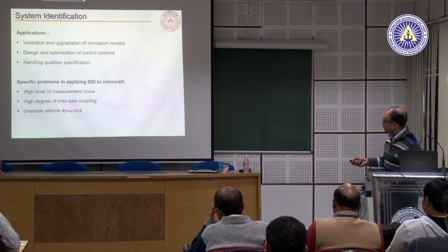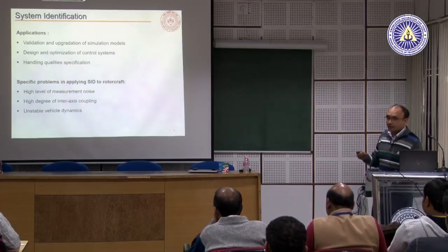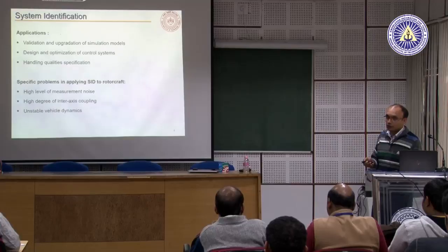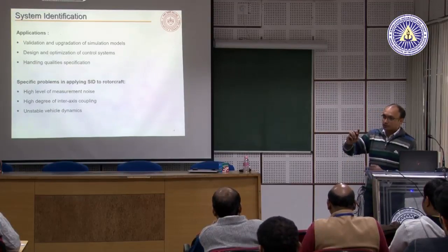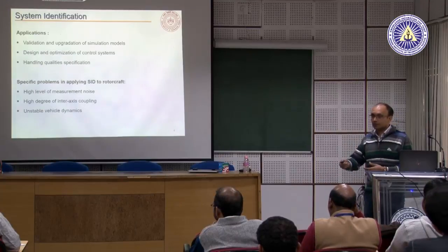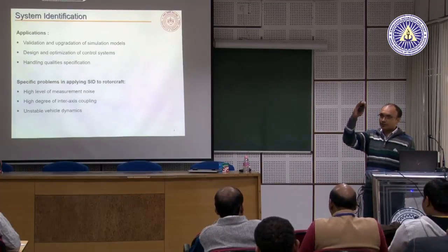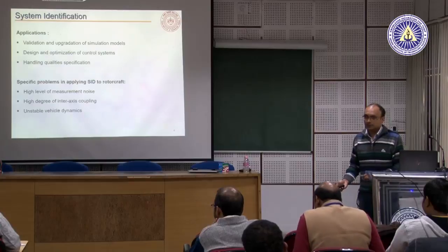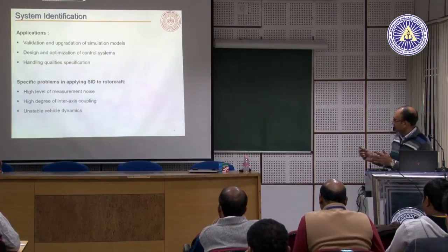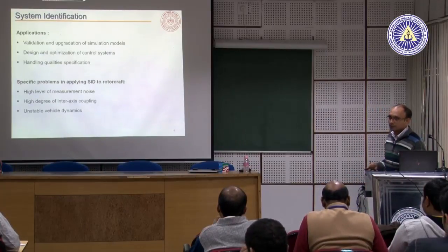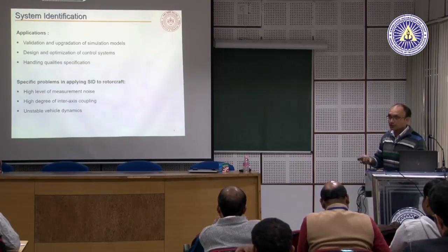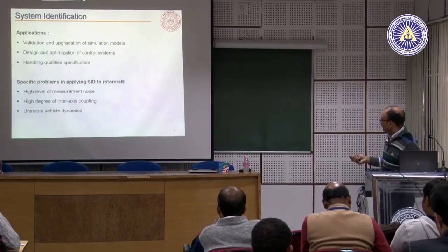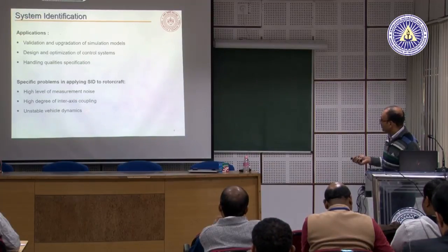And this we have also highlighted earlier, that there is a significant amount of cross coupling. We discussed elaborately how one particular motion always results in a second motion. If my helicopter rotor pitches up, it will also try to roll to one side. So pitch and roll are tremendously coupled at all times. There is coupling even between blade motions, flap and lag are coupled because of Coriolis acceleration and so on. So there is a high degree of interaxis coupling.